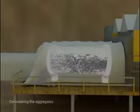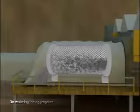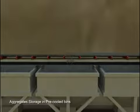Water from the cooled aggregates is removed by passing it through the dewatering rotating screen at the other end of the wet belt. Aggregates thus cooled are then carried via a closed conveyor and stored in pre-cooled storage bins. A strike plate mechanism installed over the conveyor directs the aggregates to fall in appropriate storage bins.